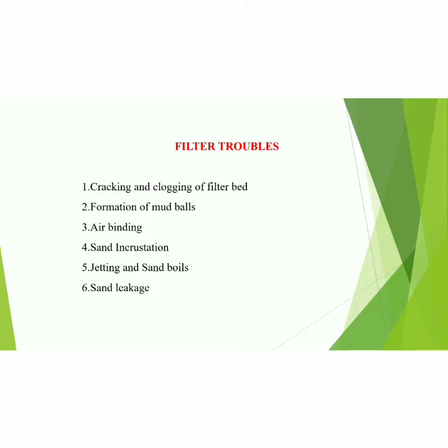So in rapid sand filters, what are the different troubles that a person gets? What are the different troubles? First one is cracking and clogging of filter bed, and formation of mud balls, air binding, sand incrustation, jetting and sand boils, and finally sand leakage. So we'll go one by one.